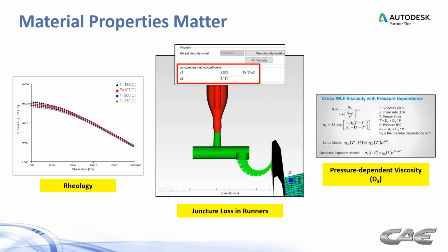We talked about material properties. For the filling process, there are really three main components to this. If you wanted to assign some weighting to this, I'd say 95% of it is the rheology curves that you see on the left. So it's describing the material's viscosity, which you see on the y-axis on a log-log scale, versus shear rate.